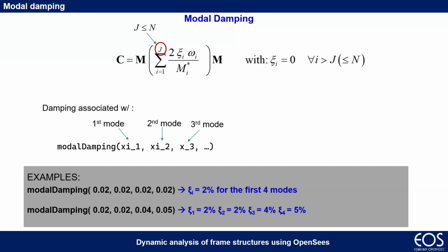And there is another problem here. My question is, there is an error before pushover when you find the eigenvalue analysis. How to solve the problem? When calculating pushover yesterday, the warning appeared. This is just, Faisal, that your structure is having a convergence problem, okay? So you have to check if maybe it's just at the end of the pushover and it's okay that you have convergence problems.